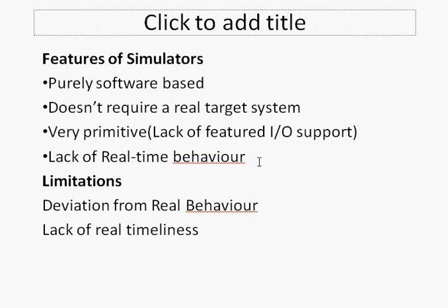Another limitation is the lack of real-time behavior. For running real-time applications, like recording a speech signal and processing it, probably a noise cancellation project, you cannot use this kind of simulator. You require a proper target with the CPU embedded in it to ensure that it gives you the desired application.